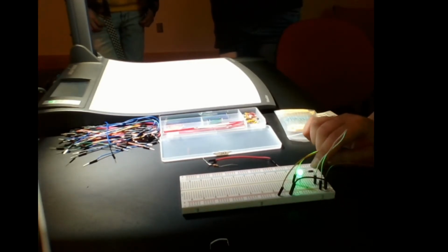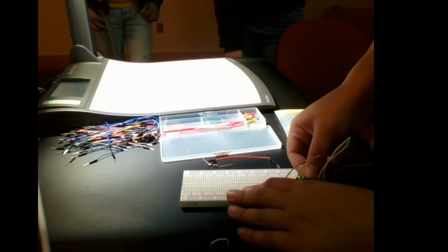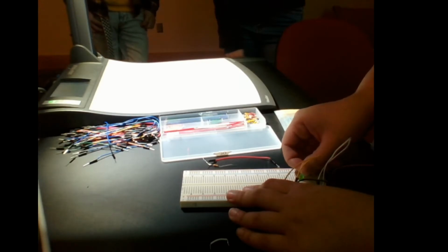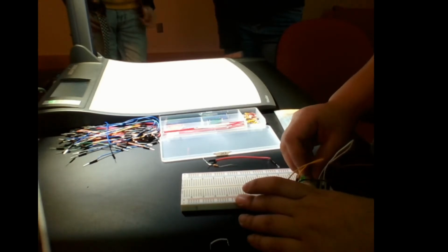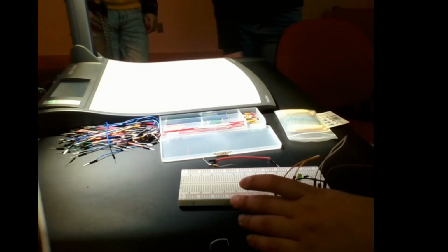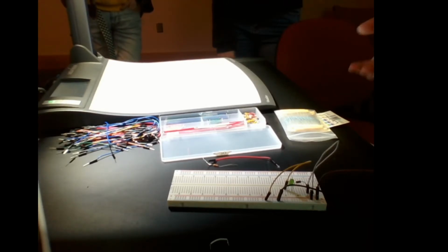So you see that the diode is in the correct direction, so that's why it's working properly right now. Now let's try to flip the diode to prove, essentially, if that's actually how it works. So once I turn it around, it's actually going from negative to positive. You might see the LED lighting up very, very faintly when I do this. It's because of residual energy, especially from my fingertips. But now I'm going to flip the power supply on, and nothing happens because the diode isn't in the right direction. Simple enough. Everybody understand? Okay, great. So that was our first demo. I have a couple more for you. Hopefully you learned something a little better by visually seeing me build one.